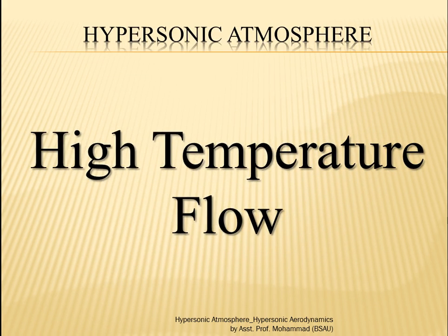The high temperature flow is also one of the special characteristics of the hypersonic Mach number. We already have discussed the high temperature generation within the boundary layer in a hypersonic flow due to the viscous dissipation. We saw that because of the viscous dissipation, the kinetic energy is converted into internal energy, which actually gives rise to the high temperature. This high temperature is not just a simple high temperature. This actually becomes so high sometimes that it can even cause the dissociation of the flowing fluid, or sometimes it can cause ionization.